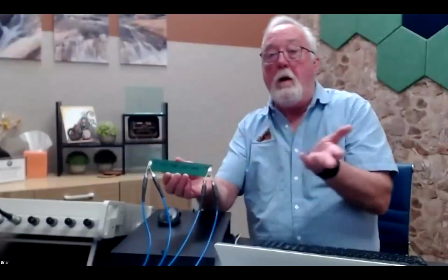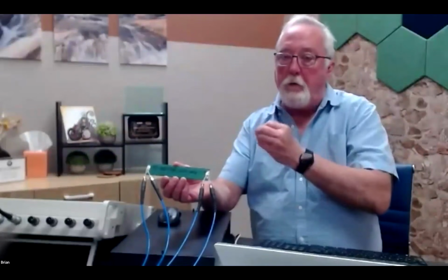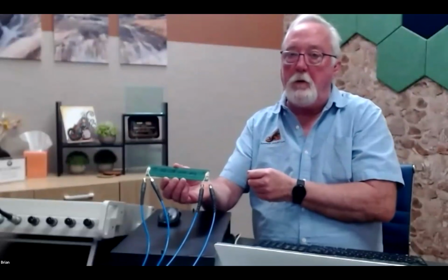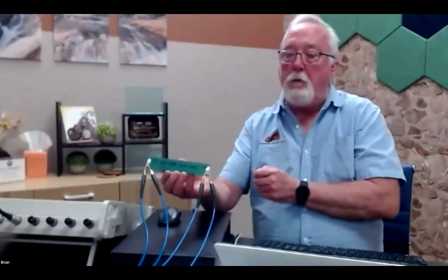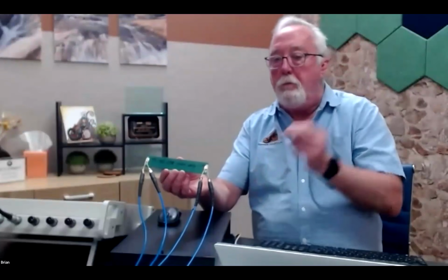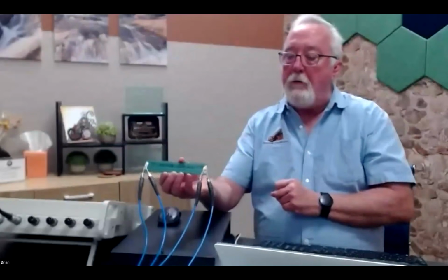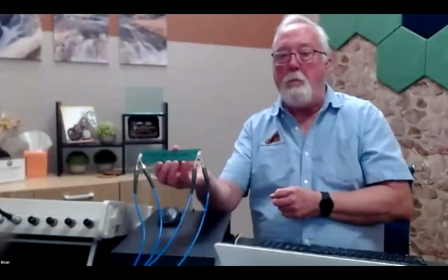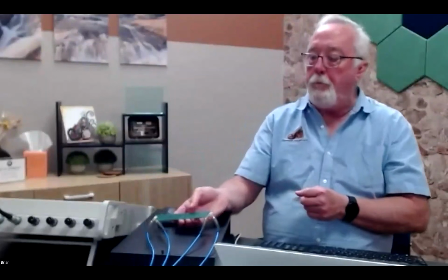Although the differential pair doesn't really need a ground plane, it does actually have some capacitive coupling to the ground plane, so it does to some extent determine the impedance of the differential pair. If you're looking at a cable with just wires, a differential twisted pair for instance, in that case you put a copper plate underneath the entire test setup, and all it does is serve as the common ground for the VNA.